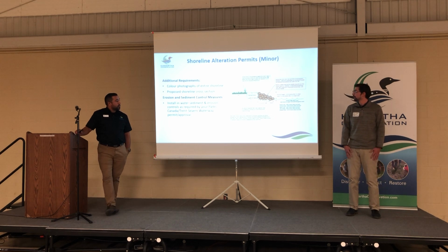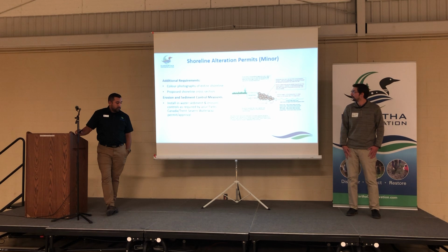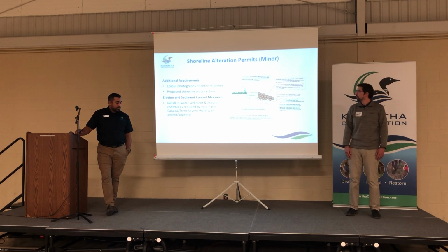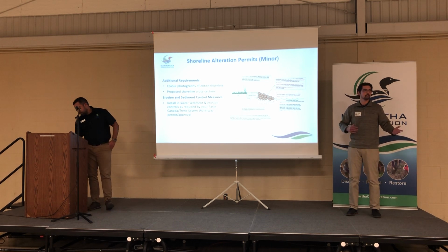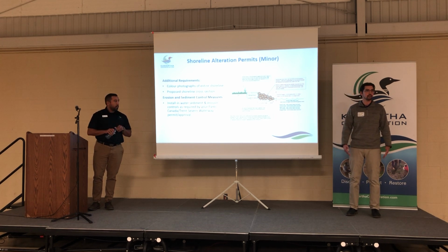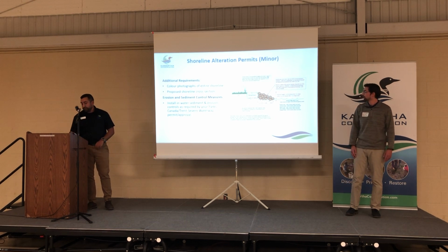For shoreline alteration permits, we did have some content about that today, but I'll go over what we would require from the Kawartha Conservation side for a permit application. There are some additional requirements for these types of applications, in addition to the other ones that I previously went over, including color photographs of the entire shoreline, generally taken in summer so we can get an idea of the existing site conditions, and also a proposed shoreline cross-section.